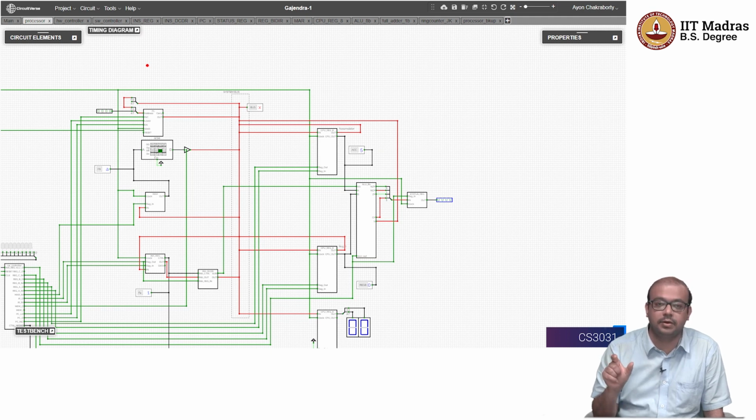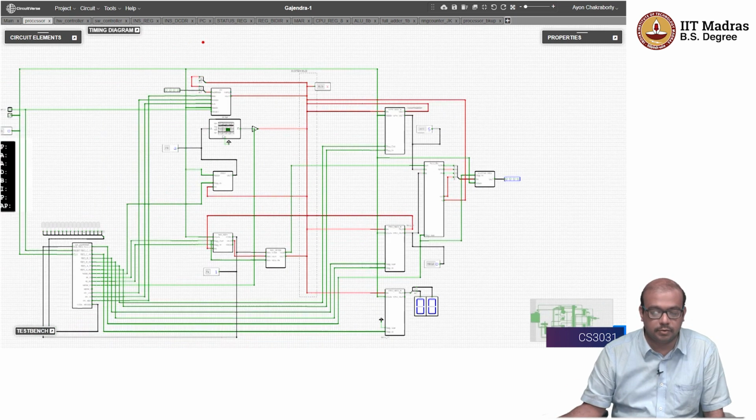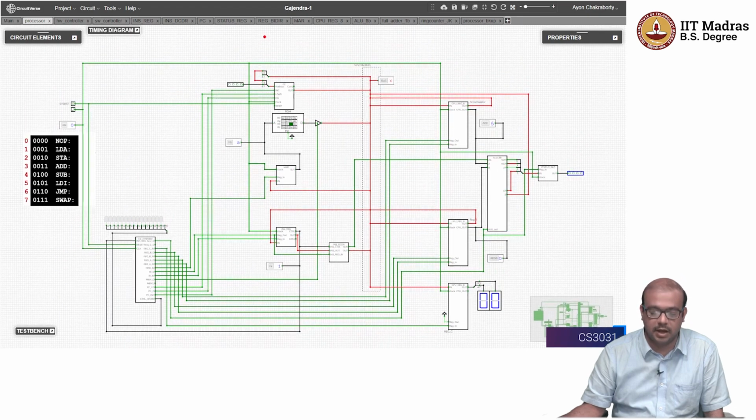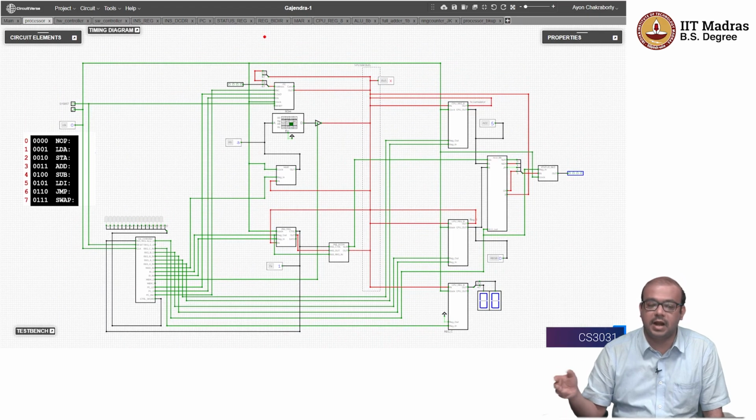The rest of the micro instructions will be just simply a 0, because I have not done an intelligent counter that resets once the useful micro instructions get executed. So if it is a 3-bit counter, I am counting from 0 to 7, and if only the first 3 micro instructions are important, so 0, 1 and 2, after it is done, the useful work is completed. So 4, 5, 6, 7, whatever, those will be just NOP kind of a thing. It is just going to be zeros.